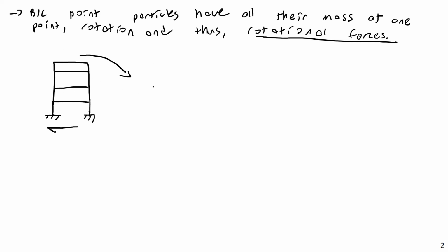So the whole idea of modeling this rotational force is that you're actually trying to prevent it from moving. You're going to say, okay, we know it wants to rotate under these forces, but what kind of strength do we need to have in the legs here in order to prevent it from falling over? And so often in civil engineering, at least, when we're looking at moments, we're saying, okay, what kind of forces do we need to prevent rotation? And same thing in statics. We're saying, okay, yes, this is not a dynamics problem, but what kind of forces do we need to apply to prevent rotation?